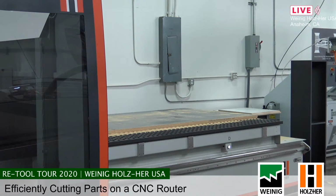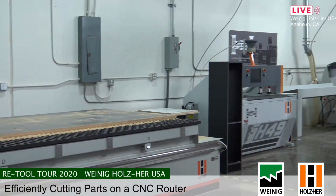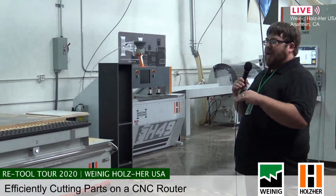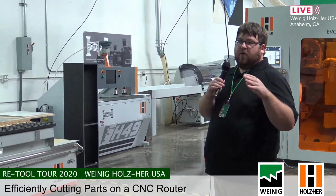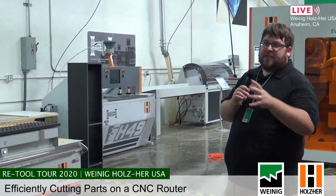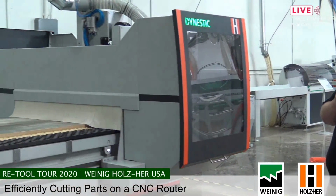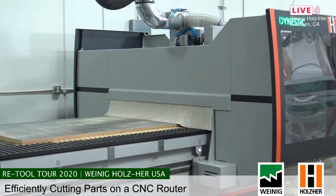So technically right now, the machining is done on the top, but only to a degree to where there's still actually some material left. And that is just so we achieve a nice uniform vacuum and able to hold the pieces down. Because the last thing we want is one of these pieces coming loose and either tearing up the machine or possibly even tearing up the material itself.